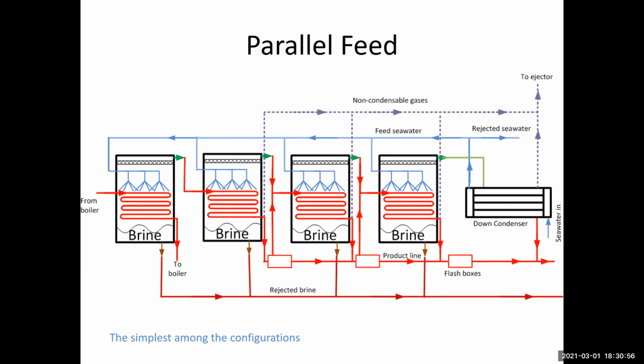And what we may also notice is that definitely it has one benefit: the vapor which is coming here does not have to preheat the whole quantity. It only preheats a fraction of it. If we have 4 effects, then basically you are heating 1/4 of the flow. So you may need less energy from the power plant. This is one benefit. But there's nothing free. This benefit is coming at the expense of something else. I hope somebody has noticed that.